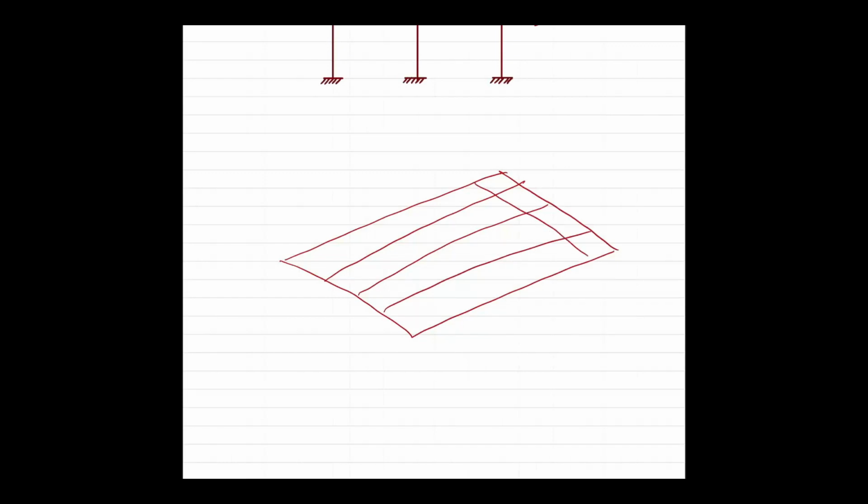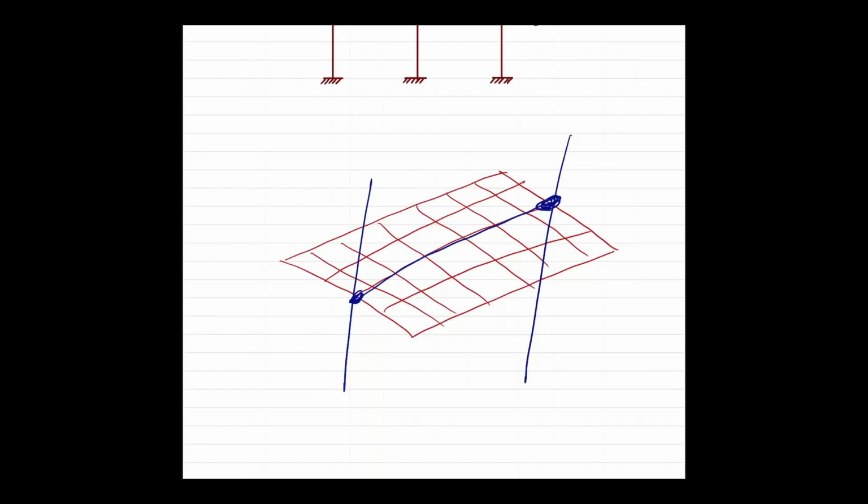This is an example. I show this example. I think it is very relevant to this class. When you design the slab or when you analyze the slab using the shell or the plate element, the nature of finite element is, the more discretization, the better the result is. So the slab you discretize, make many shell elements like that. Whereas for the beam, you might not do that. You might just say, okay, my beam is from here to there, and here is the column. And you make all this, and you understand that the program will take care of everything for you. The program will understand that, hey, the slab goes down, the beam has to go down along.